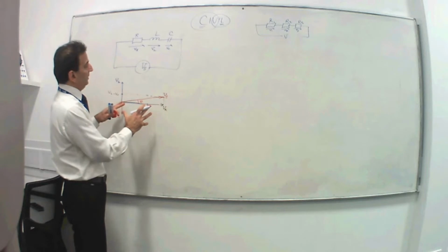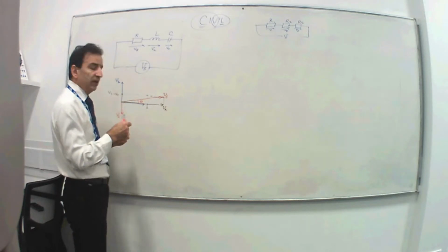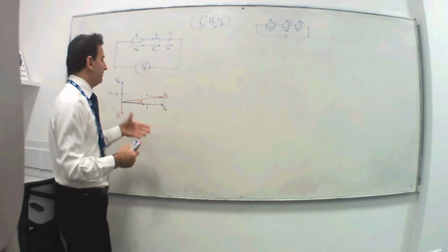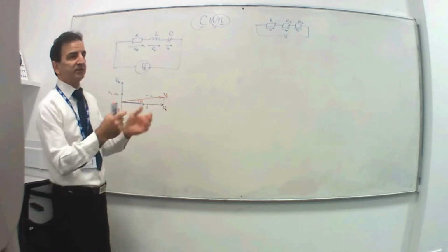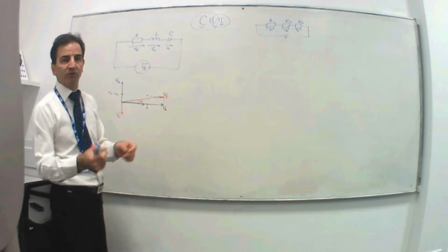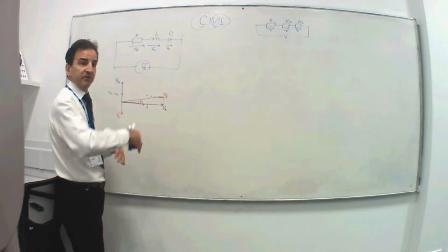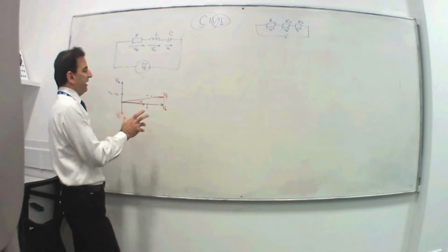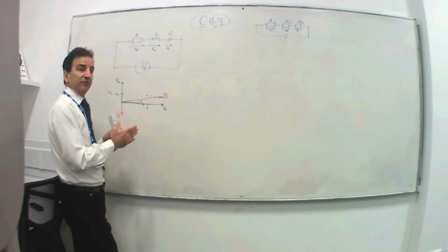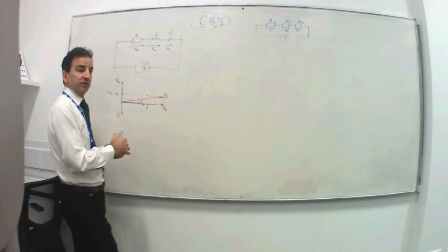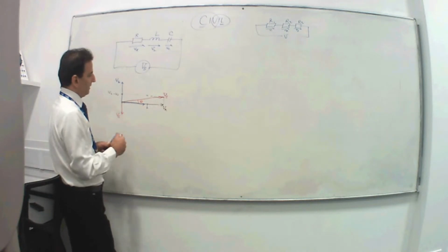How do we actually calculate this? Now, there's three methods to do this. One method is just draw it to scale. Let's say every centimeter or every millimeter is 1 volt, or 100 volts, depending on how much you have. You can have two scales, one for voltage, one for current. You don't have to have the same scale for voltage and current because they're different ratings.